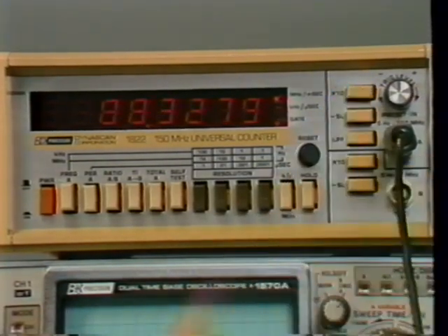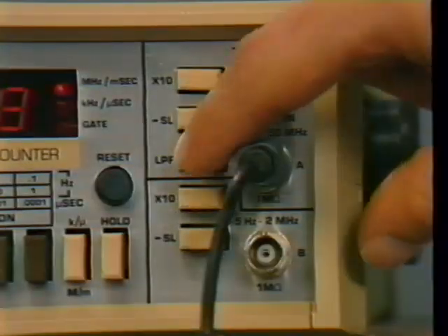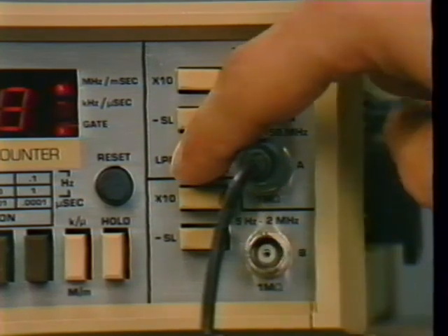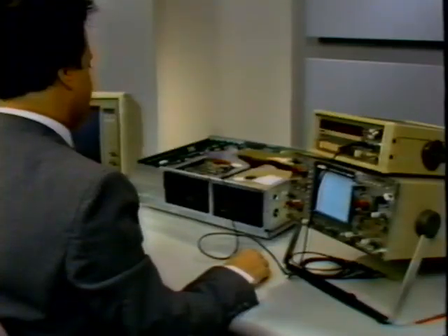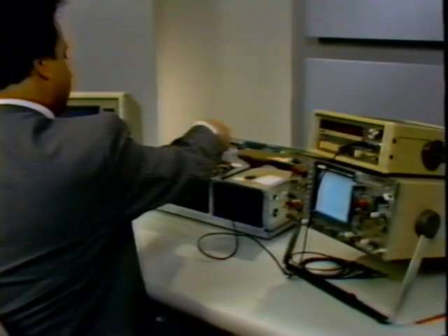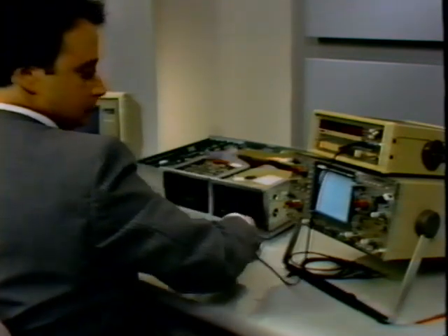This attenuates the signal by a factor of 100, which makes triggering impossible if the input amplitude is low. Finally, using the low-pass filter option on signals faster than 5 kHz will result in incorrect readings. Before leaving the subject of frequency counters, let's look at another use to which we can put them.